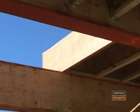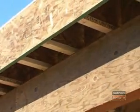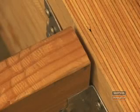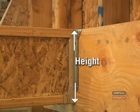A joist can rest on top of or be attached to the face of a header or beam. That's why a joist is also called a carried wood member. The dimensions of a joist are stated in terms of width, height, and length. Note what dimension is the height, because it is important for correct hanger installation.